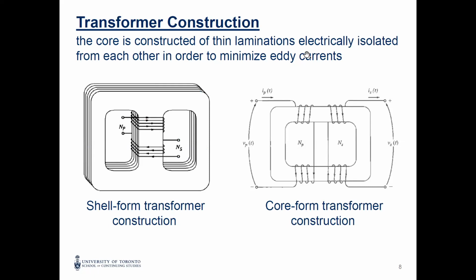And regarding the laminations here, we are going to explain it more. But as I said in the beginning, during the history, we made the core as very thin sheets, laminated in the direction of the flux. So this is the direction of the flux, right? Let's say the flux is moving here and there. So the laminations are in the direction of the flux.